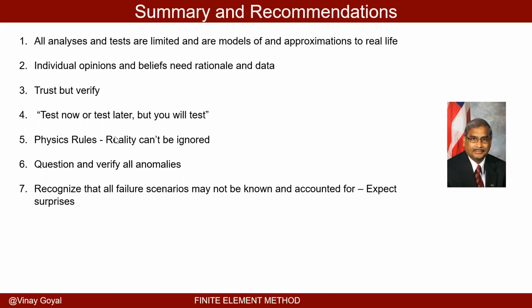Finally, you have to recognize that all failure scenarios may not be known. When we do a big finite element analysis, all the failure analyses are not known. You are making a model which is a representation of reality. That's not reality, but it's a representation of reality. We are trying to do the best we can to represent reality, and we are trying to find out what failure scenarios can occur, and we are hoping that we have covered all the failure scenarios. I can give you example after example where we missed the failure scenario and we got caught on it many times.